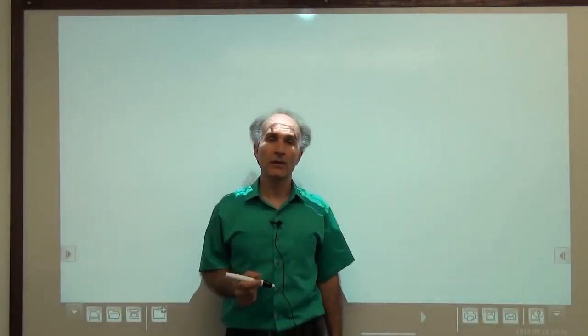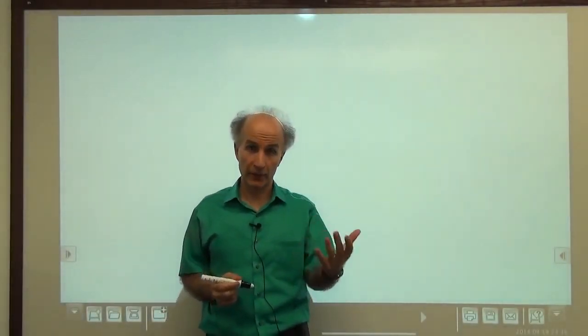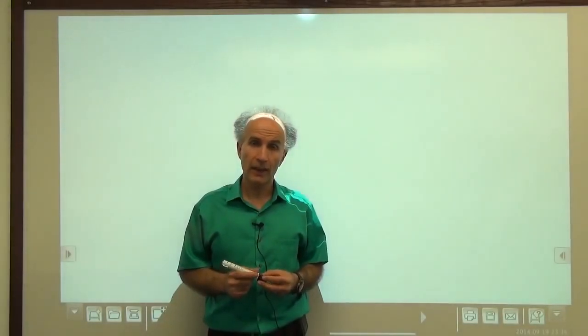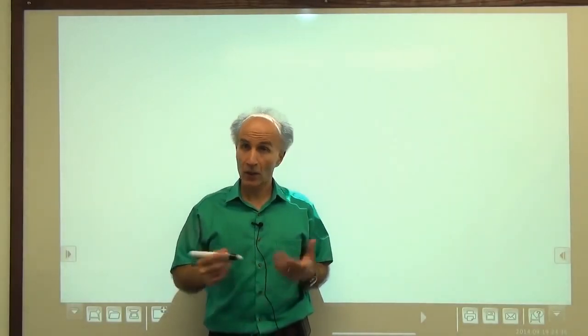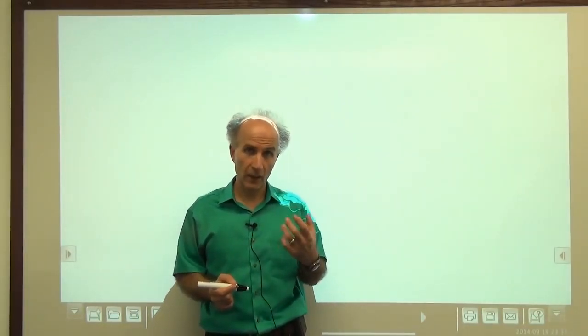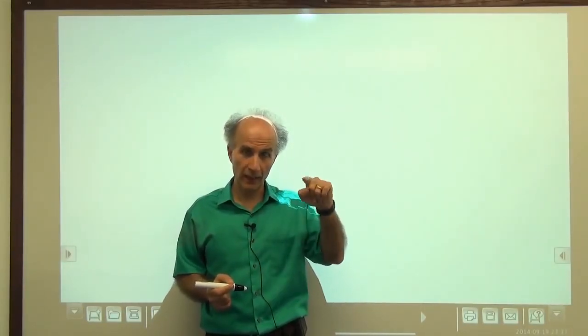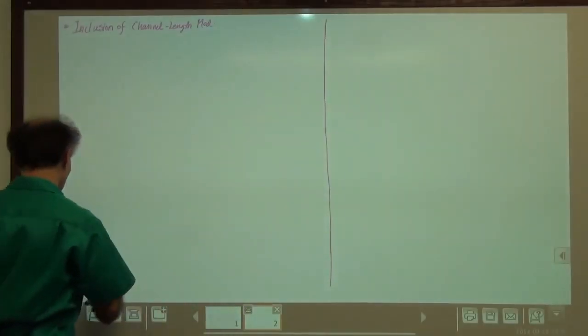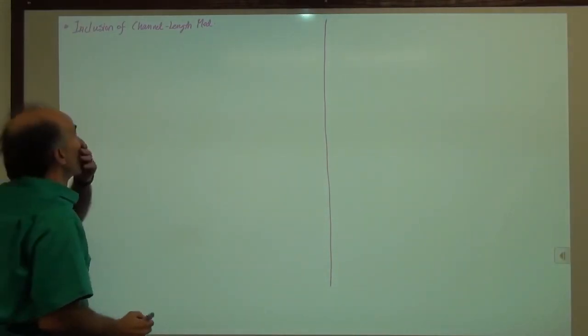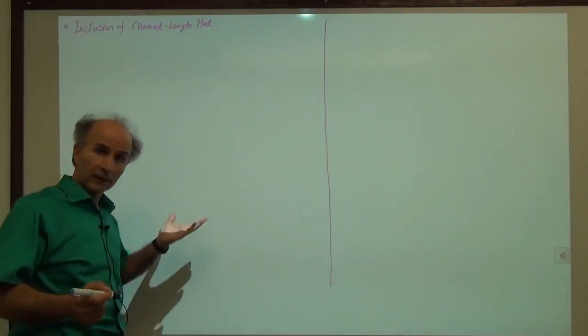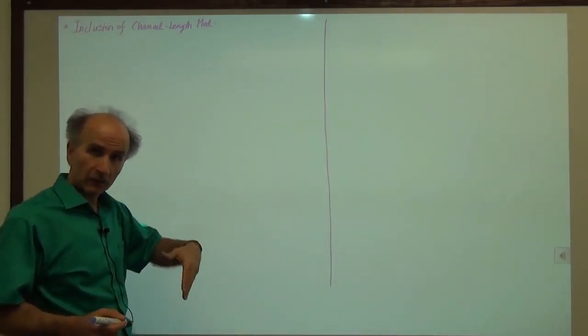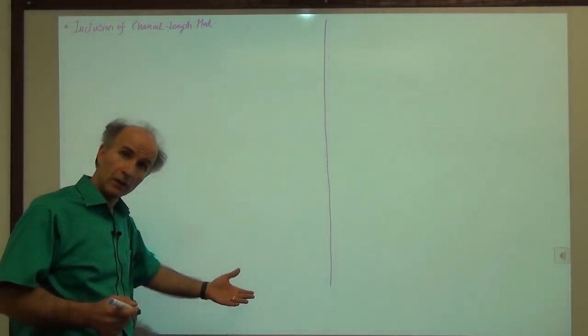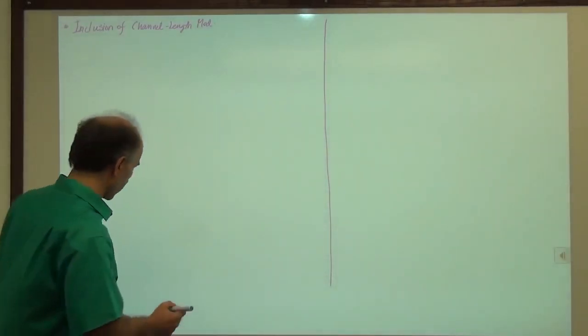All right, so now that we have analyzed a simple example of a common source stage, let's go ahead and include the channel length modulation effect in the amplifier and see if the results change. We saw that the gain of the circuit was given by minus GM times RD, RD representing the total resistance tied between the drain and AC ground. Okay, so how do we do that? Not that difficult. We go back to our circuit, draw the small signal model, include the RO in the transistor model, and then calculate. So that should be easy.